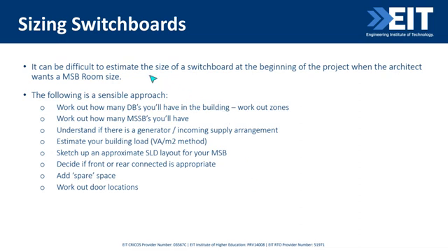So often the question is, how big is my switchboard going to be? And it can be often difficult to size a switchboard without actually knowing who would be building it. We need to know the switchboard size in order to size our room to make sure we have all those clearances. So often what you can do is come up with what we call a skeleton single line diagram for your main switchboard.